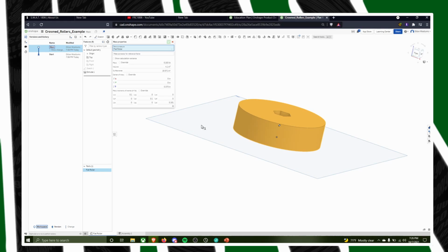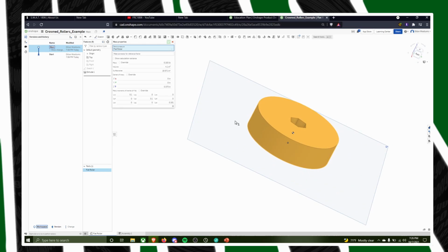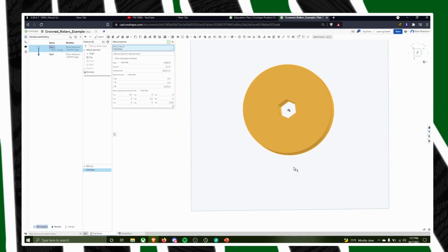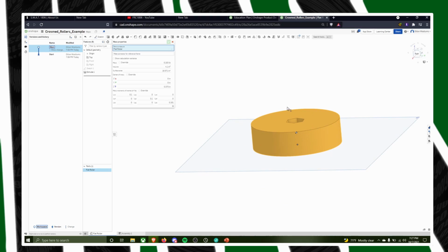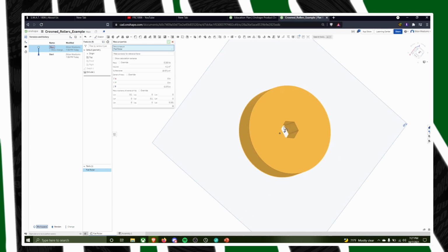So that's why I'm probably going to go with something like 50% infill on this. Oh yeah, and it shows the center of mass, which is dead on in the center, luckily. It'd be really bad if we made something that's supposed to spin fast like a roller that wasn't balanced at all. So yeah, that's the mass properties.